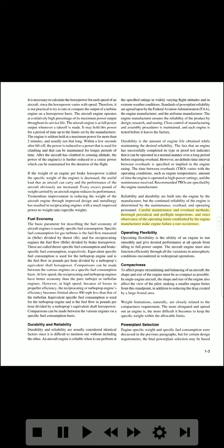Careful maintenance and overhaul methods, thorough periodical and per-flight inspections, and strict observance of the operating limits established by the engine manufacturer make engine failure a rare occurrence. Operating flexibility. Operating flexibility is the ability of an engine to run smoothly and give desired performance at all speeds from idling to full power output.